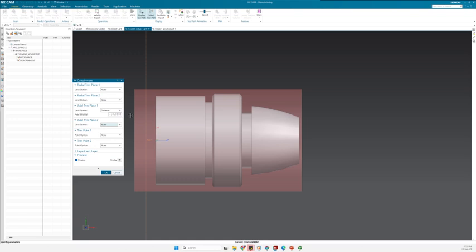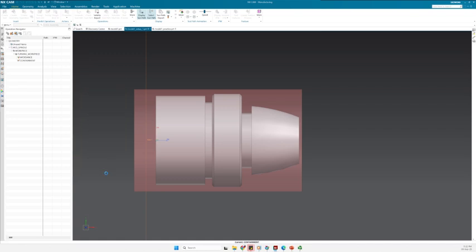You should also calculate whether this is enough space for all the manufacturing forces that you intend to put on your part. Is the spindle able to bear these forces? If not, then you need to change something in your CAD file. But supposing that this is the value, I'll just click here. So now I have the avoidance, which defines where the tool is able to start and go, and where the tool is not able to go after this containment.